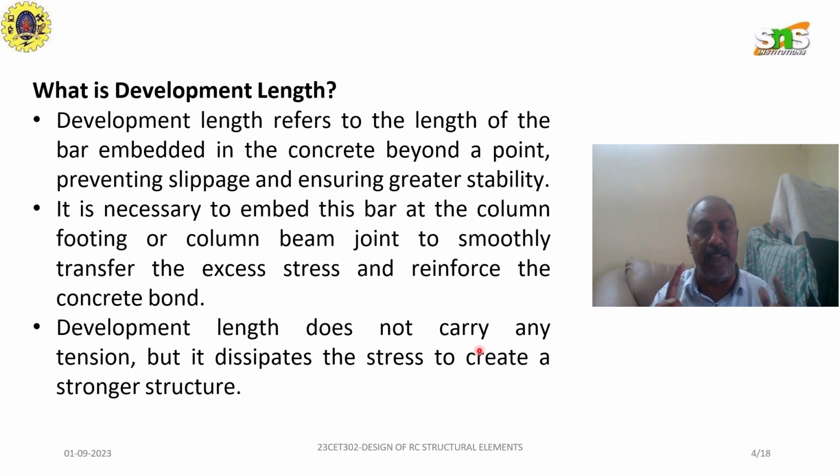The developed length refers to the length of the bars embedded in the concrete beyond the compressive stress, and this length is provided for the bond to the column.